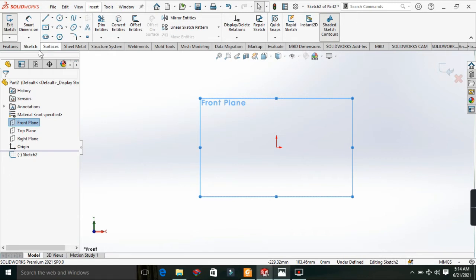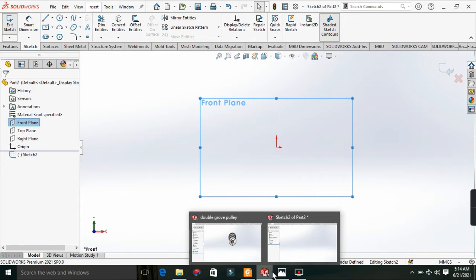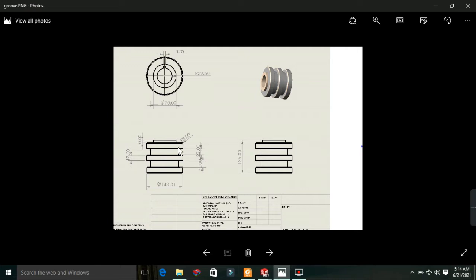Extrude Boss does not necessarily need an axis to extrude. Are you getting it? But revolve will need an axis, the direction you want it to revolve towards, either Y axis or X axis. With this diagram here, we can see that this drawing is cylindrical in shape, right? That means it revolves. So we can get this axis of revolution from the midpoint of this component.